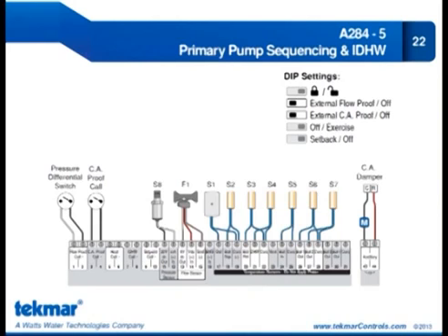But if you look at anything new, and this is just figures I've come up with based on my research, probably about 75% of the applications now use BACnet, but it's BACnet MSTP, which means Master-Slave Token Passing, and that works off a physical layer of RS-485 as well. But anything new which is going in, it's very easy to integrate. It's BACnet IP, which uses an Ethernet jack.